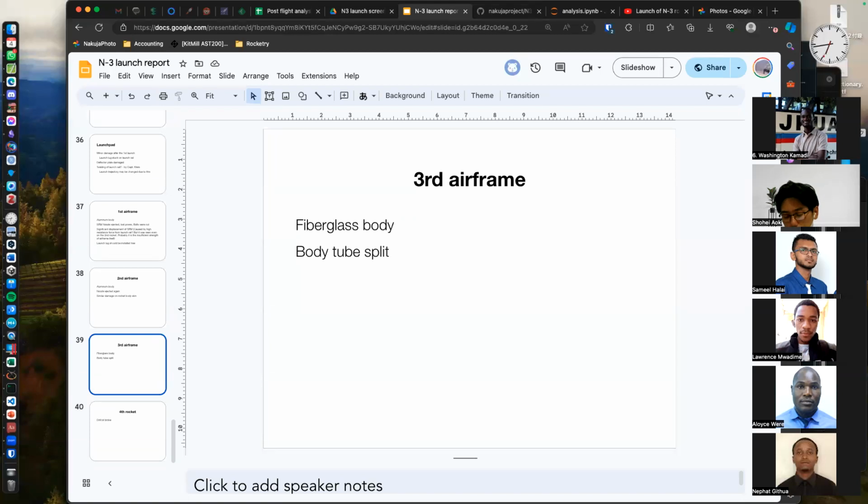So that we eliminate those chances of a bulkhead contributing to the failure. Then I also observed the antenna and the base station. Though we say that it was omnidirectional, there's a chance that it lost line of sight, because you could see that at a certain height we could not communicate. As one of the team members suggested, we could have a mobile base station, which would allow pointing along the flight path, so that at any point we maintain contact with the flying rocket.